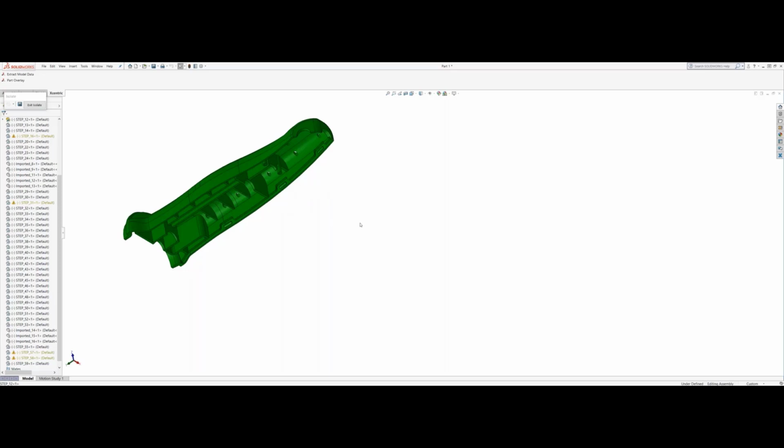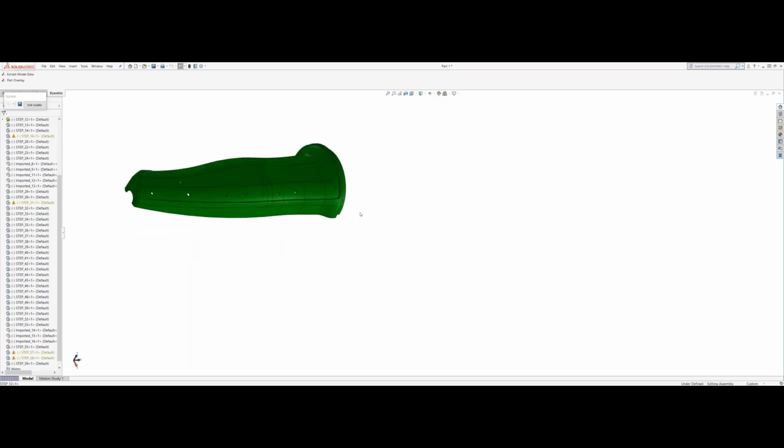As far as the adhesion goes, it's actually in the material. There was no secondary process in between the substrate and the overmold where we put a primer or anything. The VersaFlex or the TPE material that we overmolded was made specifically to bond with the ABS substrate or an ABS material.